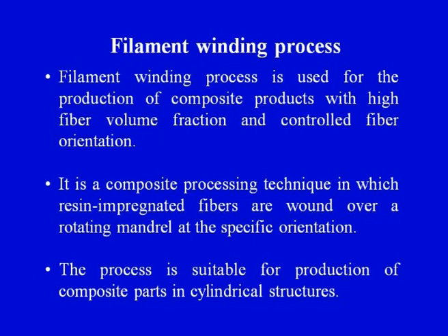So, it is a composite processing technique in which resin impregnated fibers are wound over a rotating mandrel at a specific orientation. It is a very simple to understand process in which a fiber or a filament gets impregnated in the resin bath and then it is wound over the rotating mandrel, and the fiber orientation can be controlled easily.